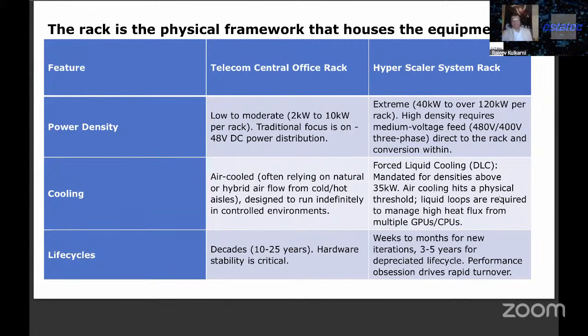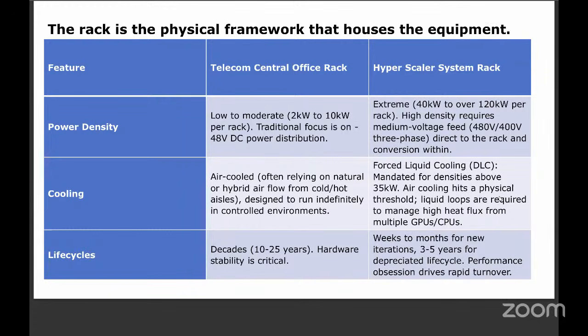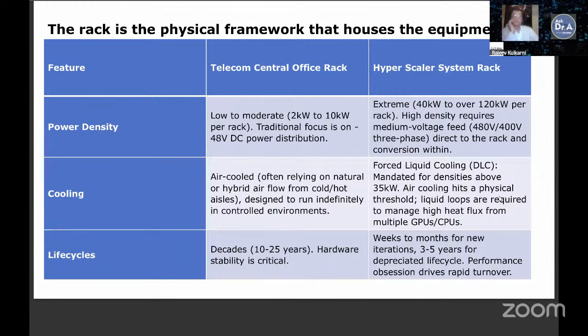The rack is again the physical framework. On this slide I've just slightly focused on power density: 2 kilowatt to 10 kilowatt per rack. Traditionally, 48 volts based power distribution. Air cooling, still air cooling is applied, relying on natural or hybrid airflow from cold or hot aisles, designed to run indefinitely in a controlled environment. 20 to 25 year PLM life cycle. I told you, even what you designed 40 years back, they are still there. If I go to any remote part of India, I see those systems, they are there. I saw a few of them in Calcutta last week when I was there.